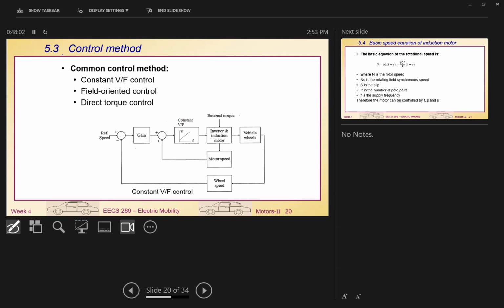Okay. So that's how the inverter is working. I think you all know that everybody tries to use an inverter for the AC. Why? Because they're using this principle. When you want to change the AC compressor speed or fan speed, to get different speeds, you need to change both voltage and frequency together. You can't just reduce the voltage using a transformer. You can reduce the voltage, but you don't do that. You change them all together. So that's the principle of this inverter, to control V and F together. Okay, we get that?